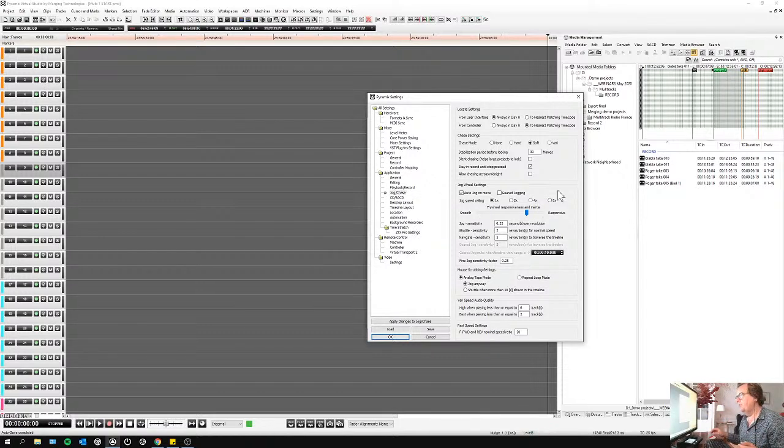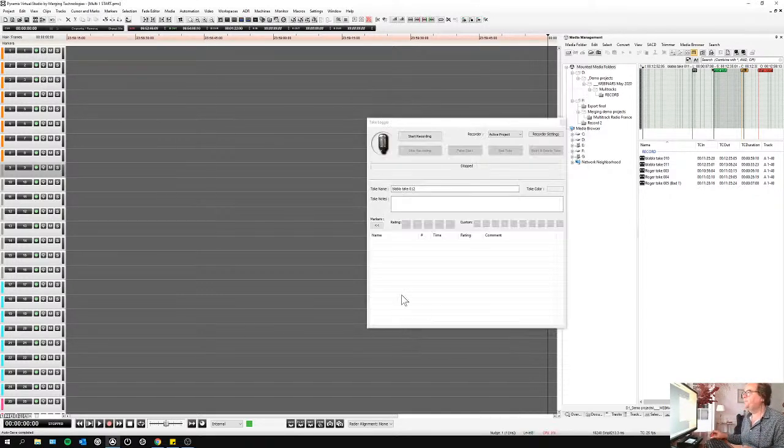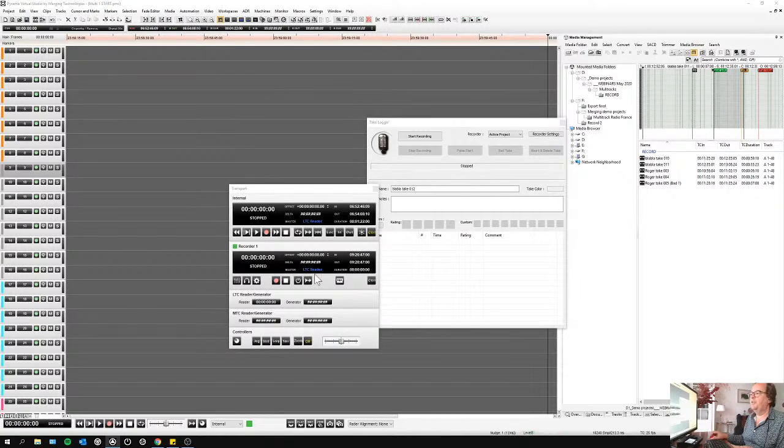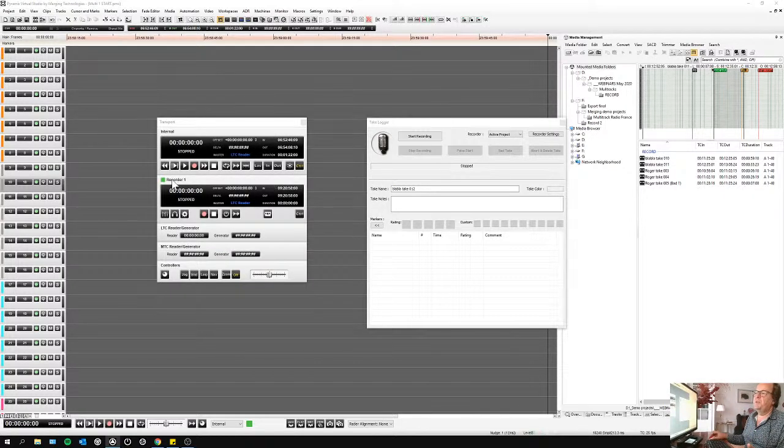So you can enable it or disable it in that aspect and go over 24 hours basically. Good. And then once you set up, you press chase down here and you go for a chase. Or you open your transport bar and you do it in your transport bar over here with the LTC reader. Okay, and this is here where you can choose the source you want to connect to. Opening this transport bar brings me down here to, I have a recorder 1.